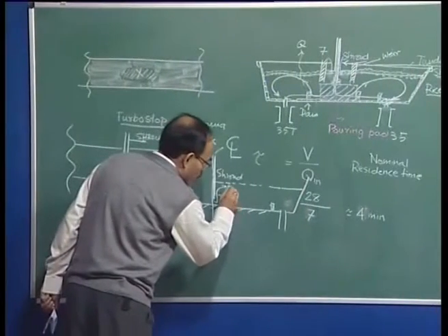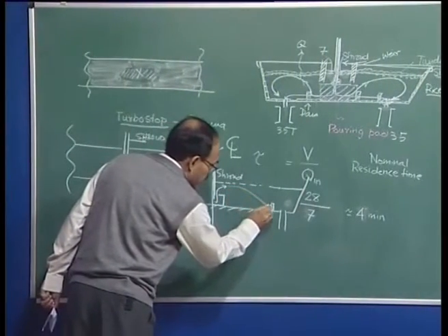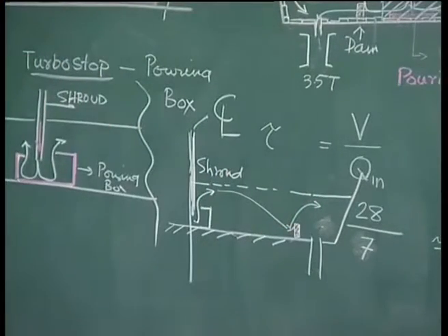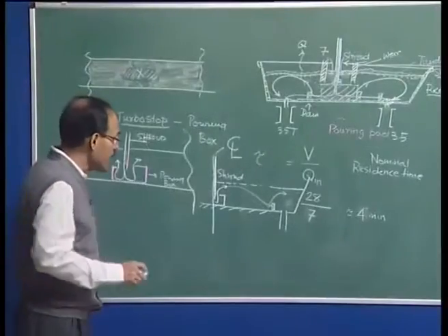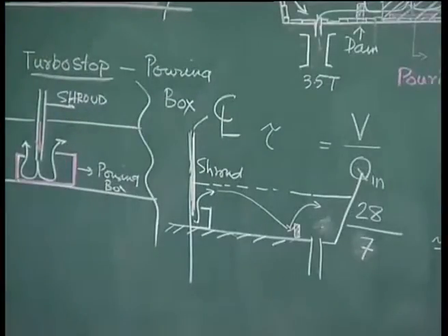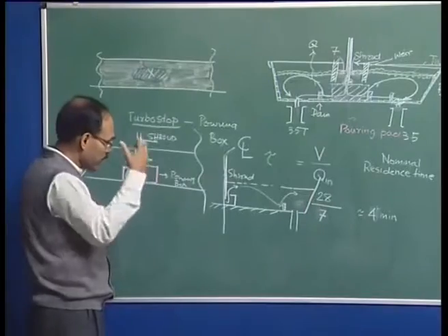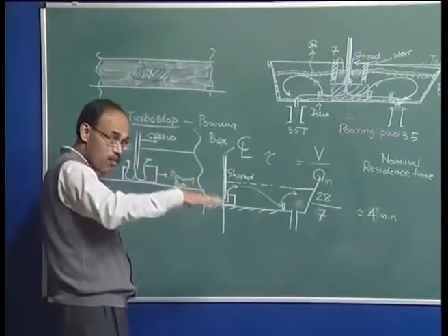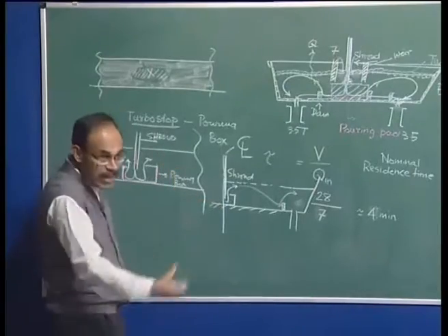So, even though it is going to approach from here, it cannot go, then again it is going to rebound from striking the dam. But the most important function of the dam in an industrial tundish is to prevent strand freezing, because when the first metal comes in from the ladle, this metal is not very hot because it is sitting at the bottom of the tundish and heat loss has taken place.